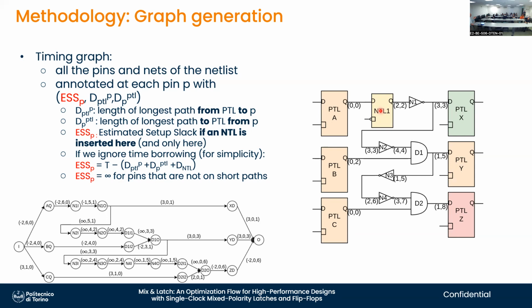So at the end, what we're doing is we use post-synthesis timing. We do optimization based on post-synthesis timing, which is less accurate, but we don't waste any time doing a very accurate job that we then throw away completely. And we let the final layout only to happen on the optimized netlist, not on the initial netlist.